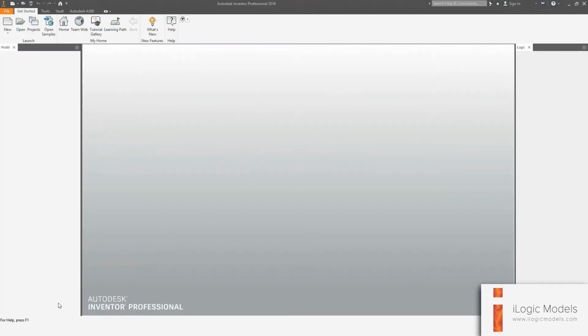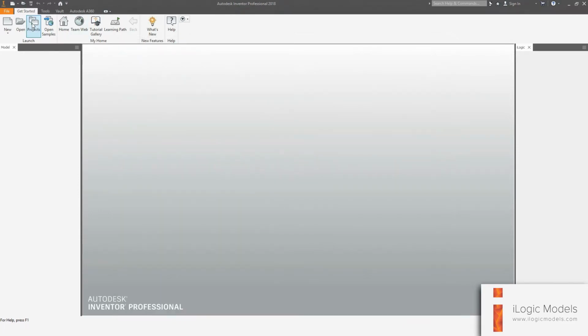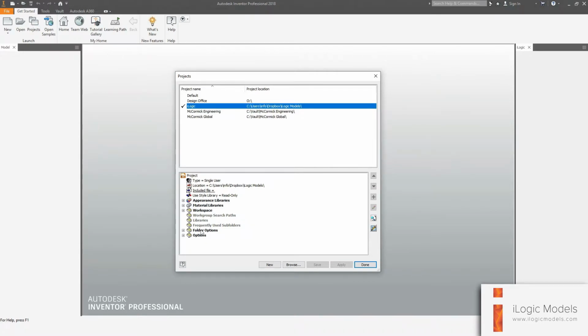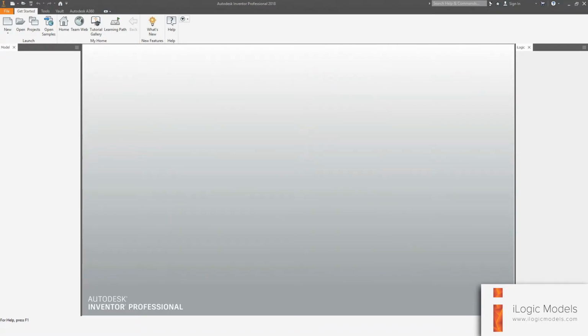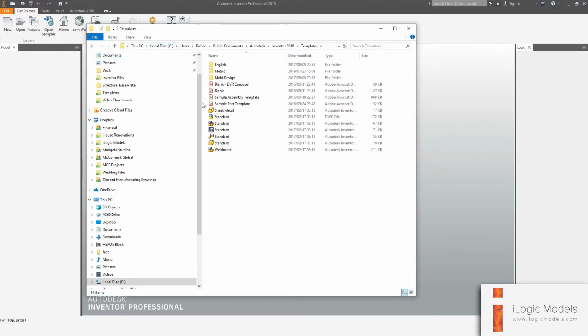Okay. We're going to go to the Inventor Templates, and then we're going to copy these two files. So how to get to the Inventor Templates is you go to your Inventor, to the Projects window, the folder options. You're going to go to Templates and right click, Edit, copy this path and close this off. You're going to open a new Explorer window. Paste this path that you copied in the window, and then we're going to go create new folder.